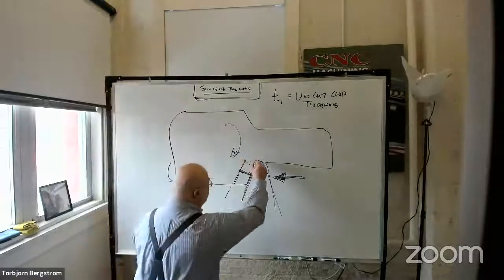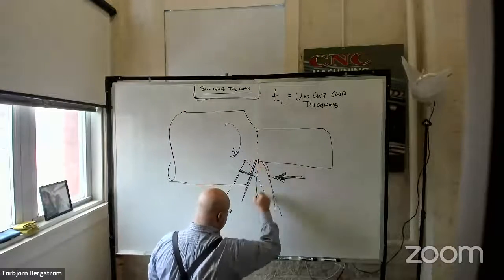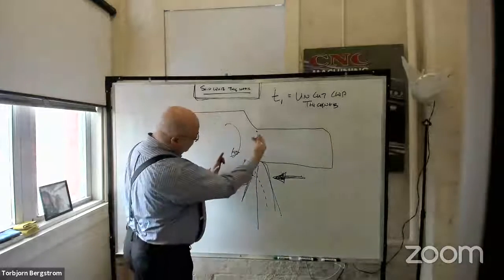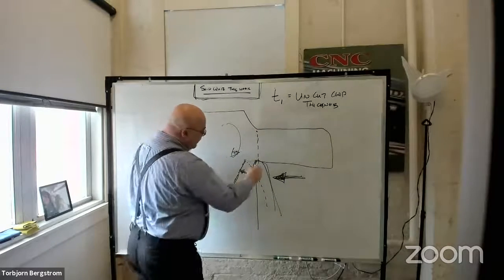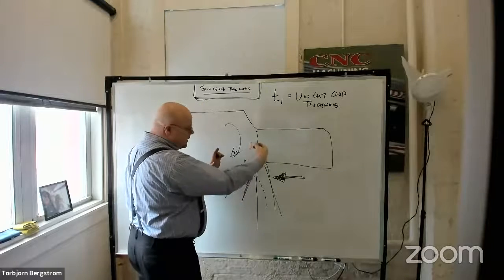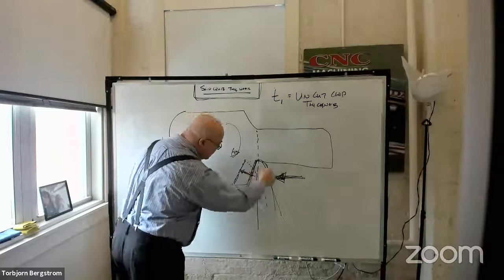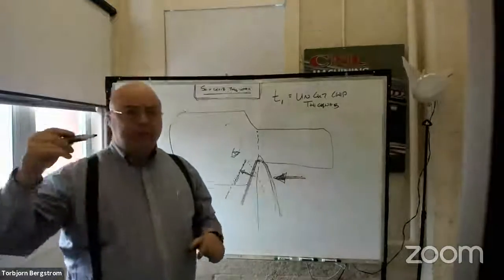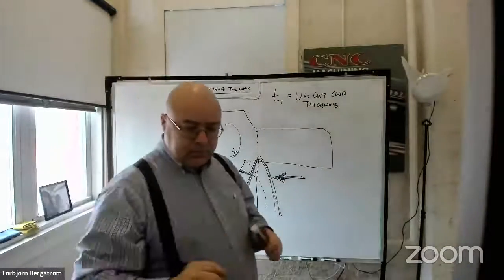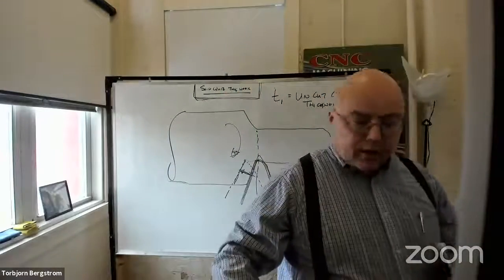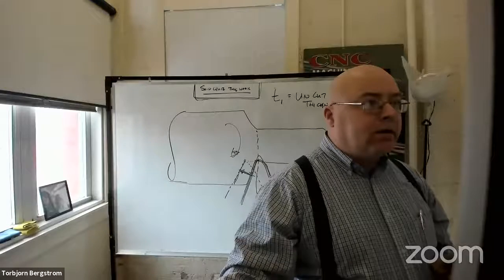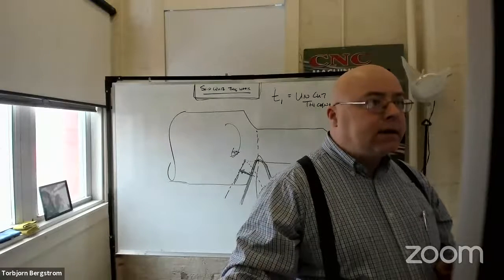And so there's an angle here from the cutting edge of the tool. So if the tool was not at this angle, the uncut chip thickness would equal the feed rate, as long as you have the right units, right? All right, but since we have that angle, it doesn't equal the feed rate.